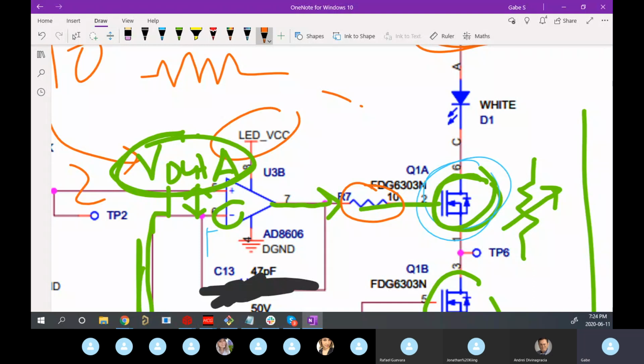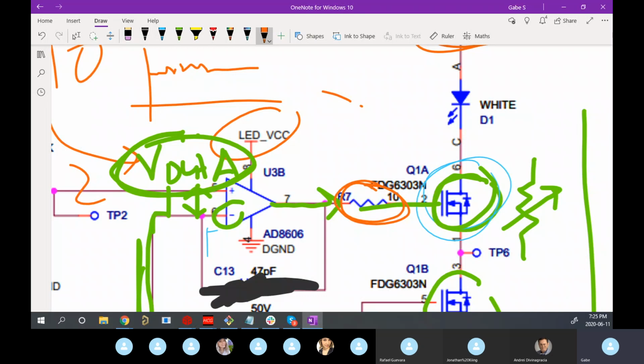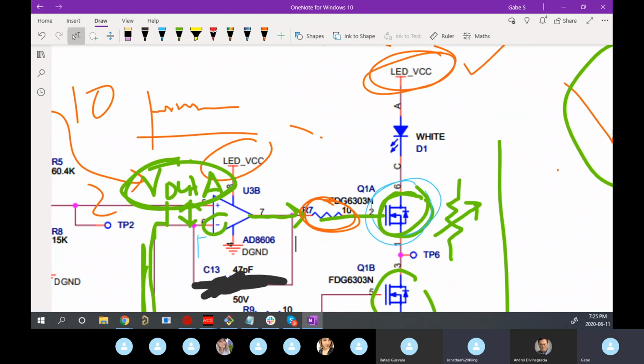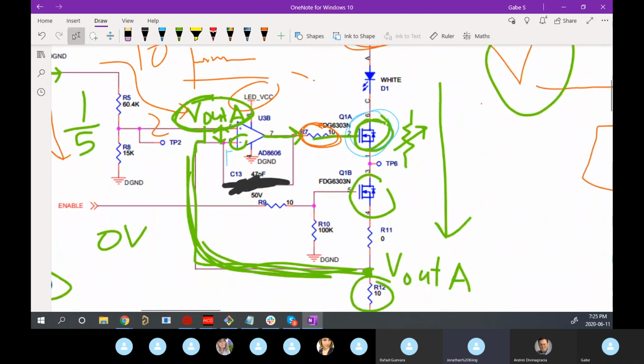And putting, I guess that's not a very clear drawing because that's a resistor. But if this is the voltage of the MOSFET gate, sometimes you get some noise on that. And so putting a resistor usually helps keep it quiet and more stable. Usually optional. When you read future schematics, if there's a resistor with no value on it, it just indicates it's a very small resistor.